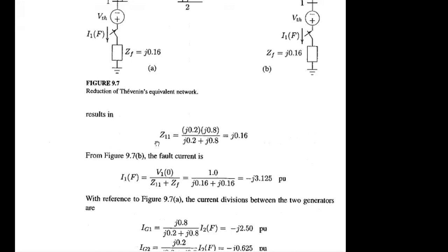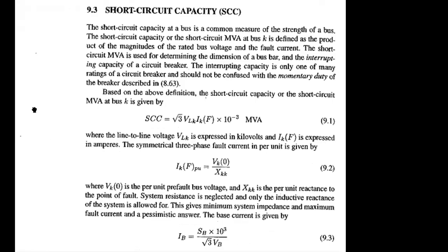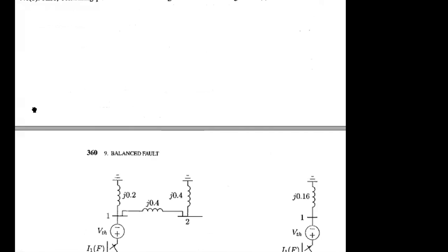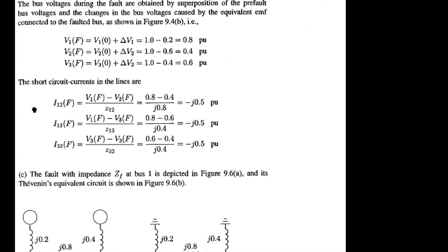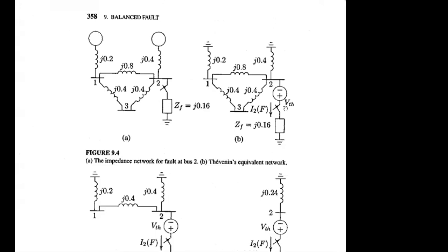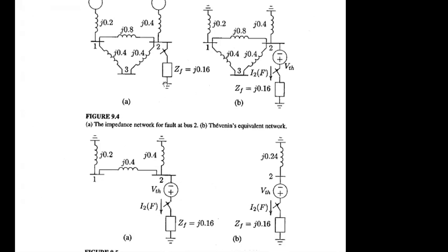So the equivalent diagrams are found by the Thevenin rule, right, sir? Yes, Thevenin rule. So there you can see you have to readjust the diagram based on the bus fault location. Thevenin rule across that terminal of 2, so you have to generate that. In that case, the equivalent will be simpler than the earlier one, because you don't need to shift the conversion now.